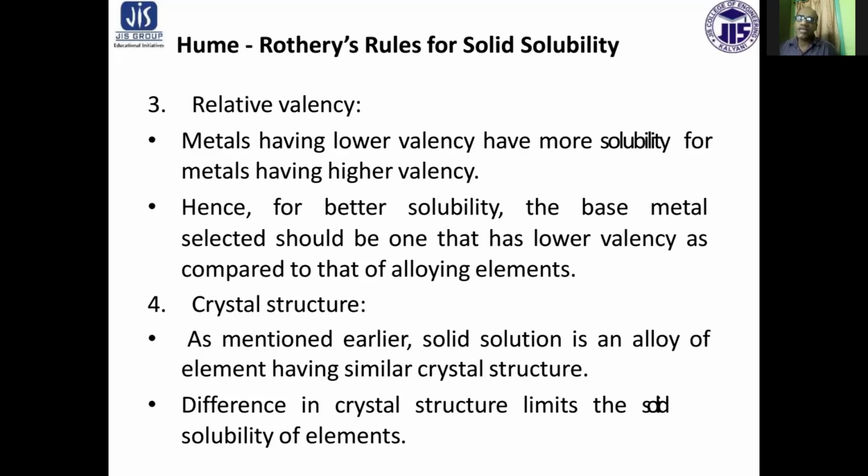Next, number three, that is relevant valency. Metals having lower valency have more solubility for metals having higher valency. Hence, for better solubility, the base metal selected should be one that has lower valency as compared to the other alloying element.